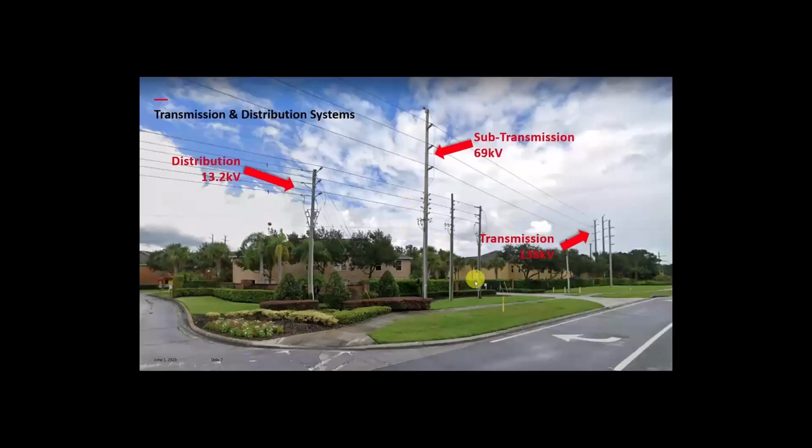Just a really quick thing. This is actually pretty close to my house. I like this area because it shows a lot of stuff going on that explains how utilities work. So most importantly to us, this is the distribution circuit. Usually the distribution that's feeding the primaries of your transformers is limited to a 15 kV or sometimes a 23 kV service, up to 25 kV. Occasionally you get a little bit higher, but probably 90% is under 23 kV, and it's going to look kind of like this.